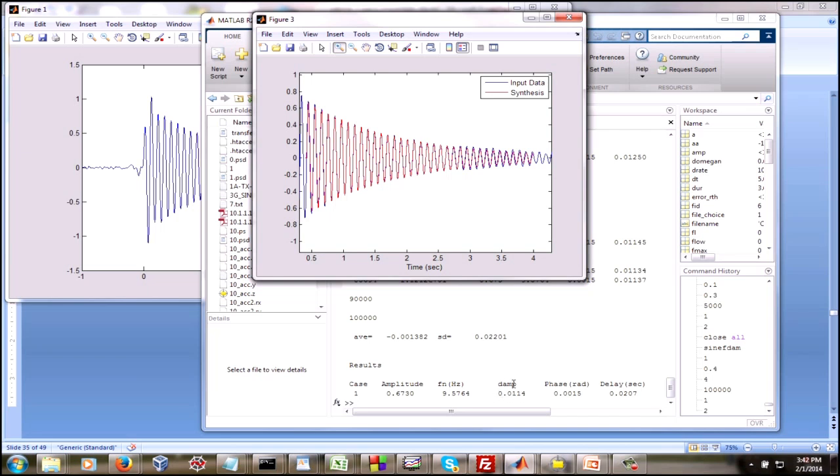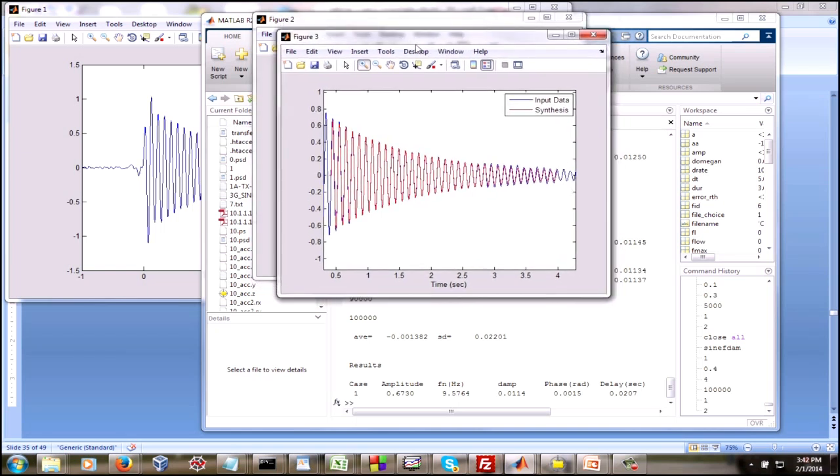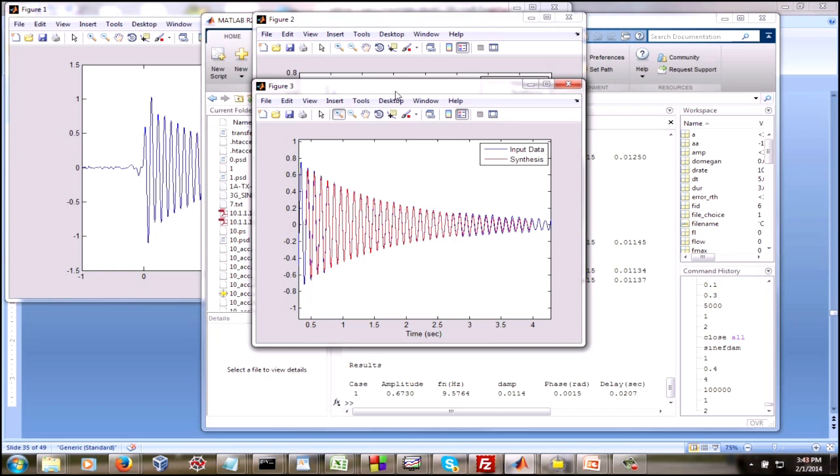And the damping ratio, usually we like to present this as a percentage. So if we multiply by 100, we'd say there's about 1.1% damping. Now this is for a given Pegasus mission with a given payload. But each payload is different, and this natural frequency depends on the mass and stiffness properties of both the launch vehicle and the payload. So that's why it's necessary, one of the reasons it's necessary to do a coupled loads analysis prior to launch.